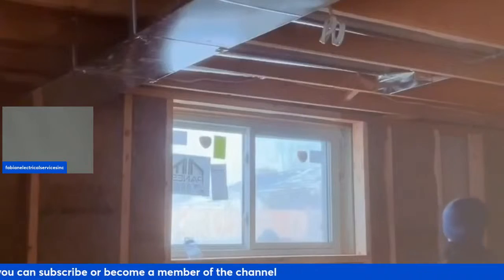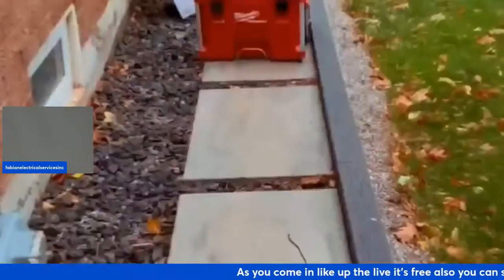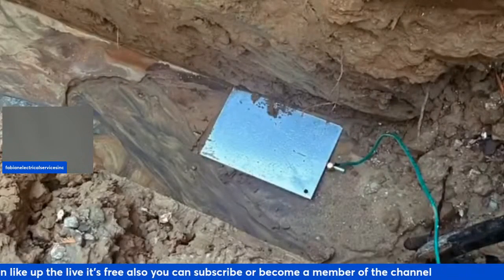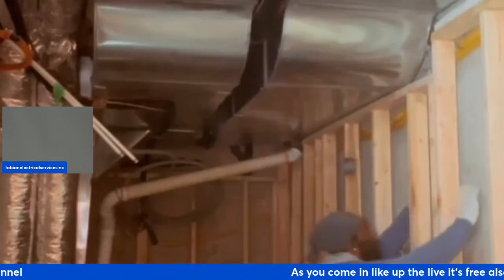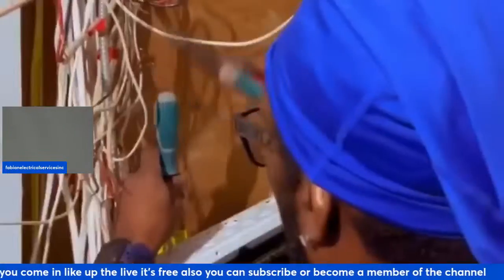We use it a lot. You can basically put that at the beginning of the circuit outside of the panel. It's going to protect it also. Or if you run your aluminum cable to the location, you can simply put it on a regular breaker and then have the GFCI arc fault in that location, where it's not really a full-size kitchen, and that's how we go around that scenario.